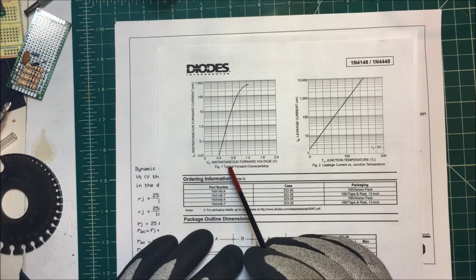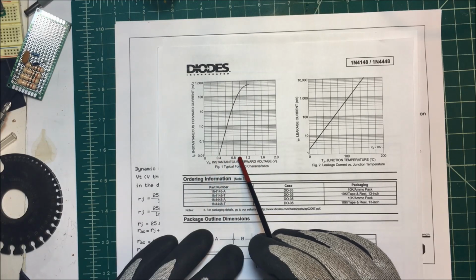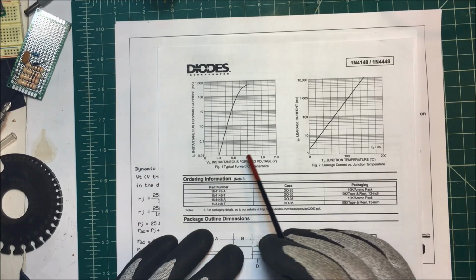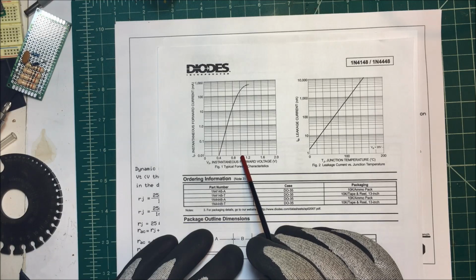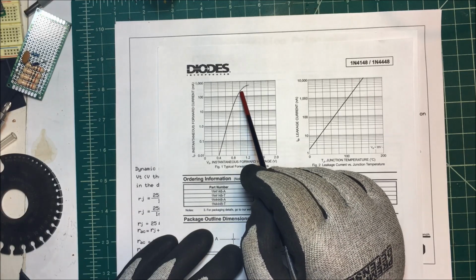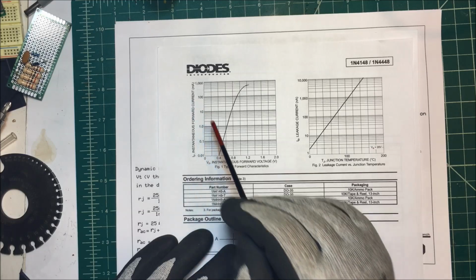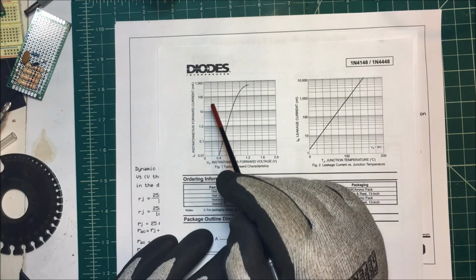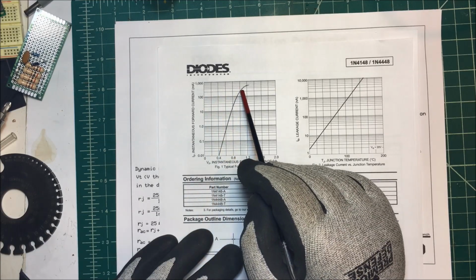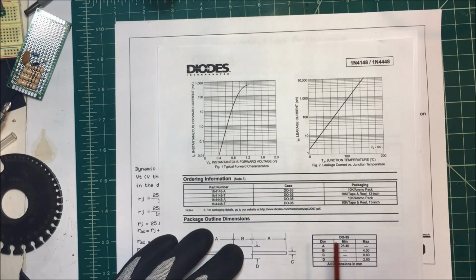And we're going to pick this here. We're going to pick a volt, and we want to pick it over the knee voltage there and get into the more linear region of the diode. So we take our 1 volt here and run this up this line here. This is our instantaneous forward voltage and instantaneous forward current. Up here, this is 100. This is a logarithmic scale. This is going to be 200. So at 1 volt, we're going to have an instantaneous forward current of 200 milliamps.